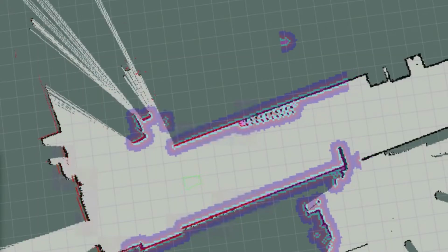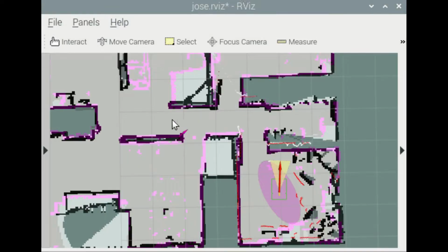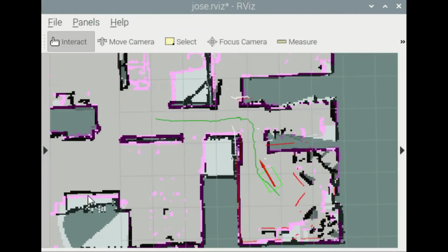Now I know ROS and ROS 2 have a lot of packages available and some decent tutorials so that you can get a robot up and running to some extent or another. You can probably get remote teleoperation working fine. You may be able to get some SLAM packages implemented with varying degrees of success and be able to click on points in RViz and the robot will navigate to those. You might even get a waypoint follower working where the robot will move from one waypoint to another within a pre-mapped area. But let's talk about that one thing, waypoint following.